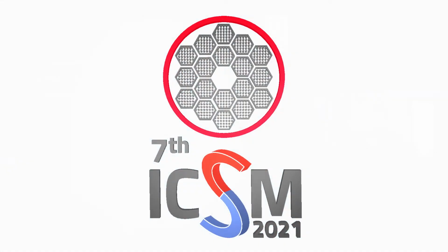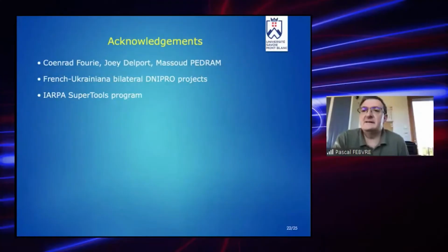Your software, of course, you are talking about one junction only. We didn't do it in this program. Indeed, we were not looking for that. The Fraunhofer variation of the critical current of the Josephson junction is modified in Jonas if you apply a magnetic field. But at this stage we cannot sweep and see interference, because we didn't put in diffraction. It's not so complicated to add diffraction, so I think it's a good idea. We could add it. It will help to see what's going on in a general circuit, and especially with larger junctions, it's interesting.